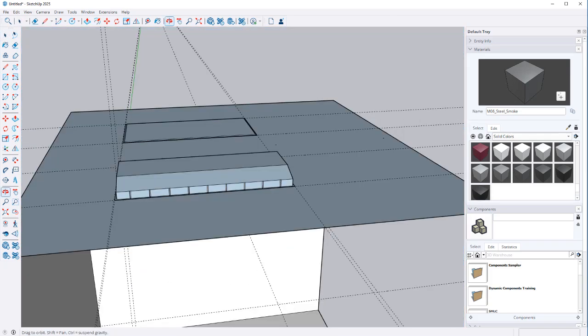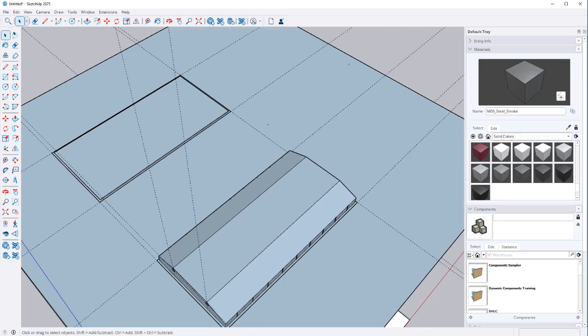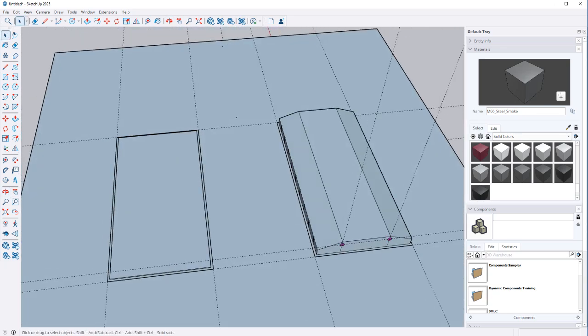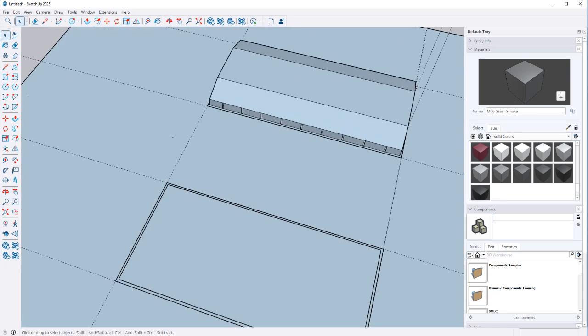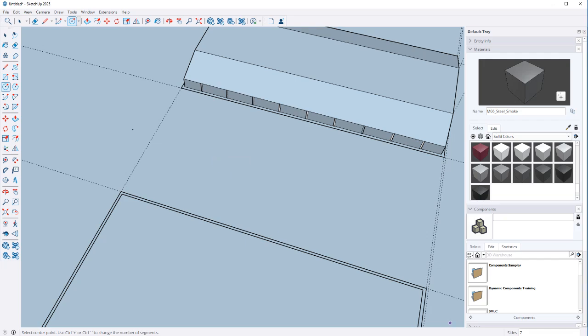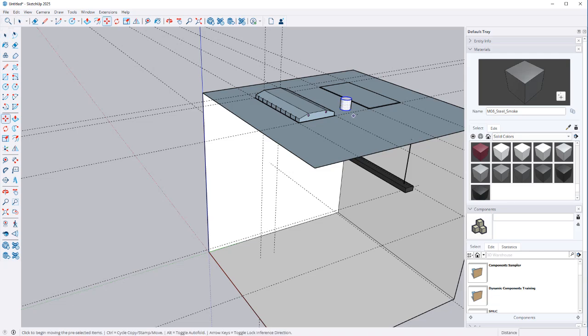Another thing you might want to work with are can lights, and they're actually kind of easier to draw from the ceiling. So let's say we've got a couple 6-inch can lights. Don't forget to change your number of sides back up for this. So I'm going to do 24 sides. We'll call this an 8-inch can light. Sorry, let's do a 6-inch can light. So we'll do a 3-inch radius on that. We'll pull this up. We'll make it about 6 inches deep. And then I'm going to pull this off.